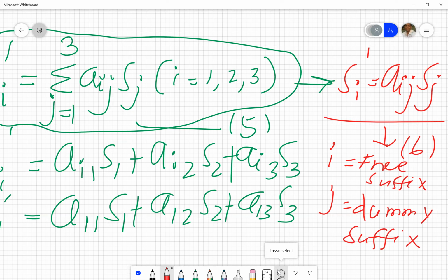As I have already told you, in a three-dimensional state of stress there are 9 components: 3 components of direct stress and 6 components of shear stress. There are generally 9 components of stress on the orthogonal faces of the element at a point.